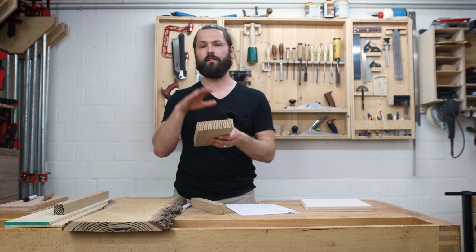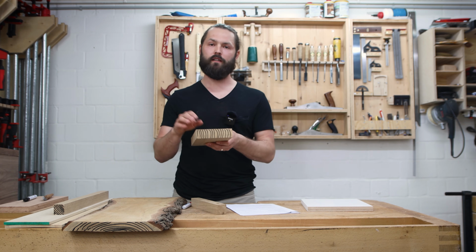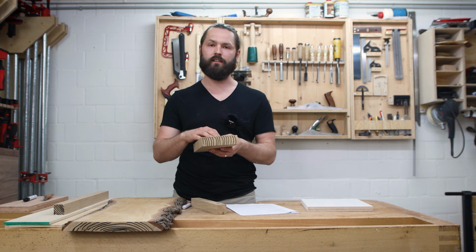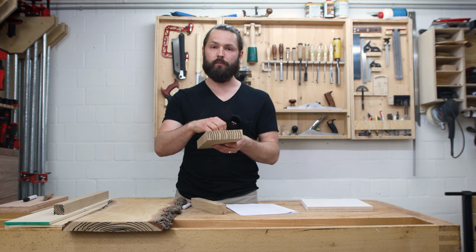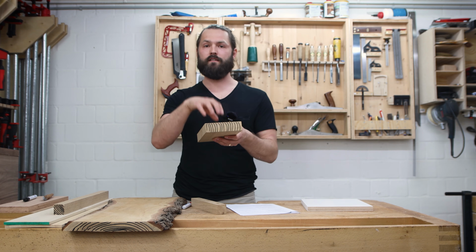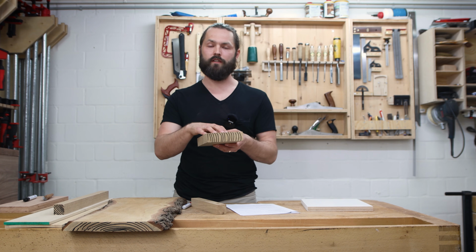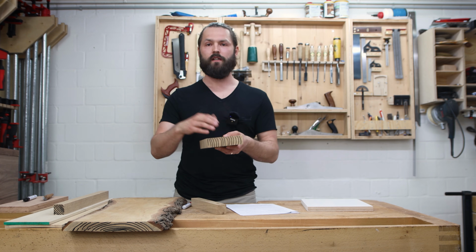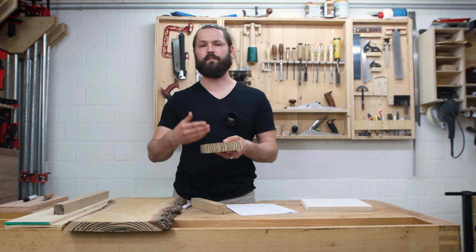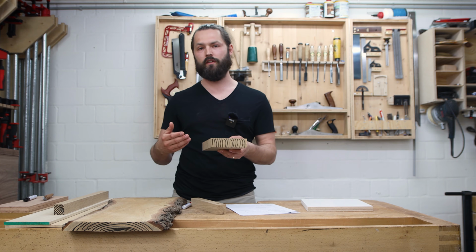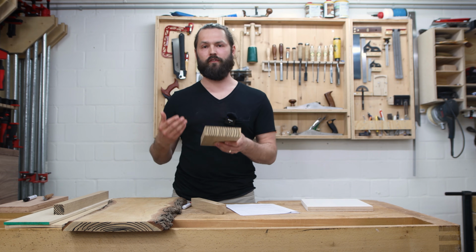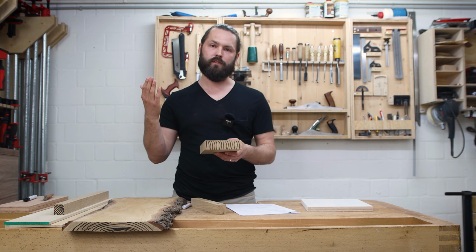I only buy kiln dried lumber. That means the lumber I buy is around 8 to 12% when it leaves the kiln. Yes, it will absorb and give away moisture as it's sitting on the shelf at the lumber yard. And it will also do that when it's down here in my shop. So my shop is in a heated place, so it's pretty much the same moisture content in here as for the final place where the furniture piece will go in my house.